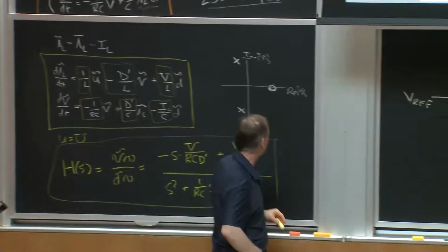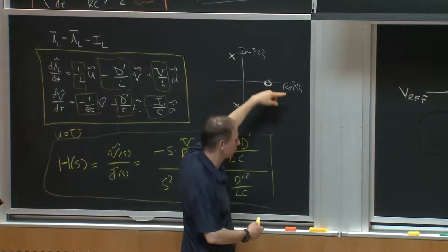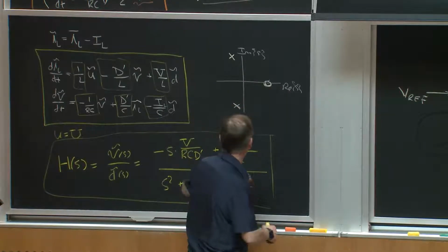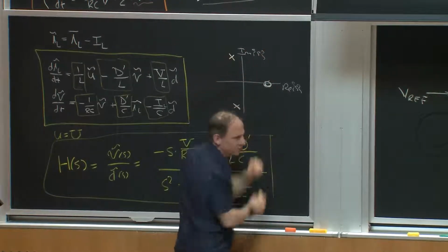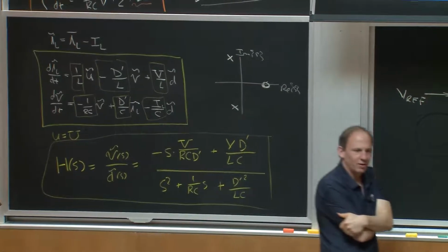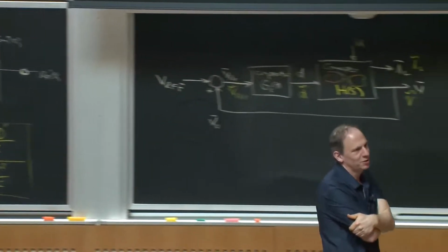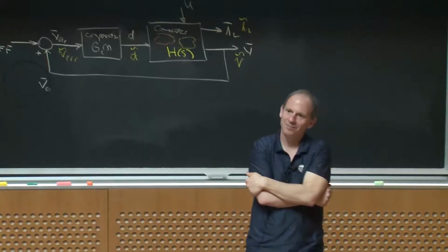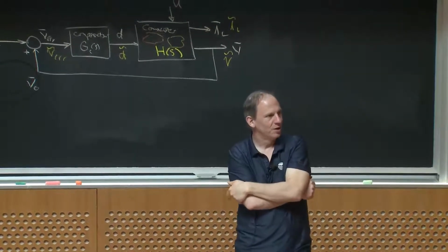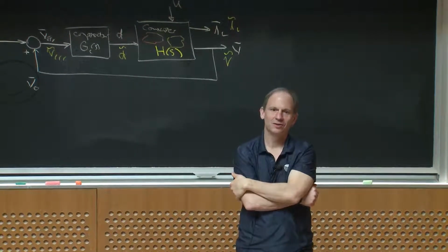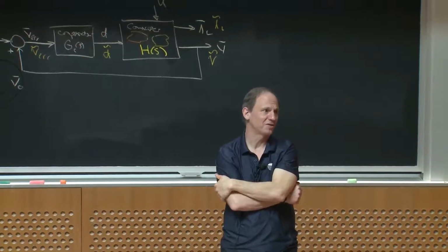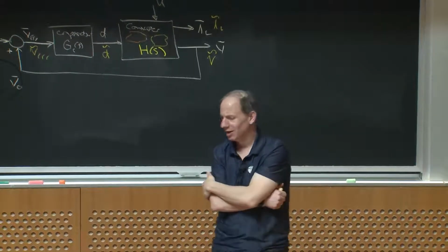And what that means is if I took this thing and put in a proportional feedback loop, the poles would tend to move towards the 0. Now, if the poles move towards the 0 and the 0 is in the right half plane, that means the thing tends to go unstable. So something with a right half plane 0 is very, very easy to make unstable, generally. Okay? So we don't like that.